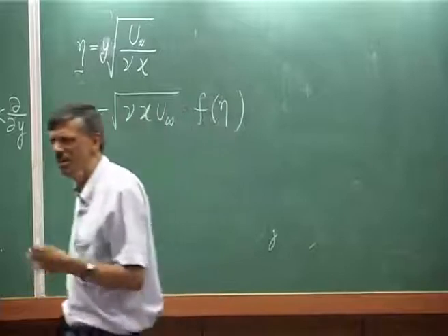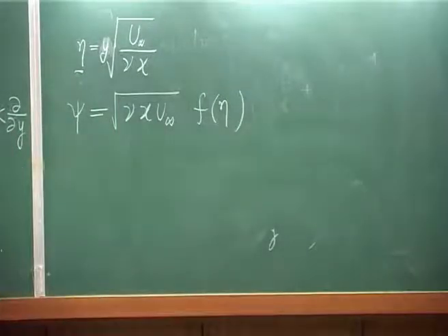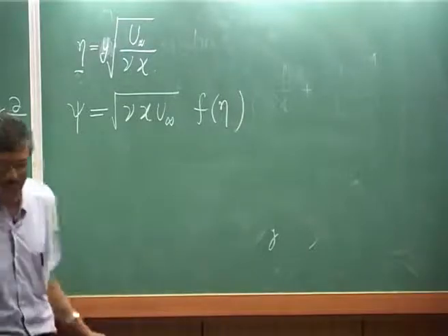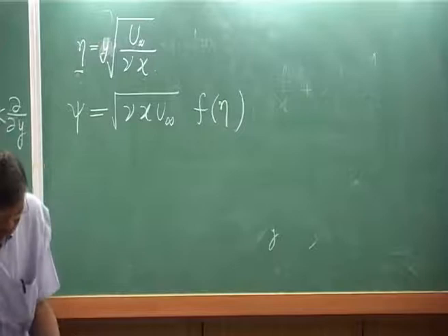So, f is some kind of a non-dimensional function, okay, and the scaling is done with respect to this. Why do we need psi? Well, very simple. I told you, never violate mass conservation, right. So, for this problem, if I introduce the stream function, I am guaranteeing mass conservation. So, this is an ironclad guarantee that you would not fall into the trap of violating mass conservation by the introduction of psi.